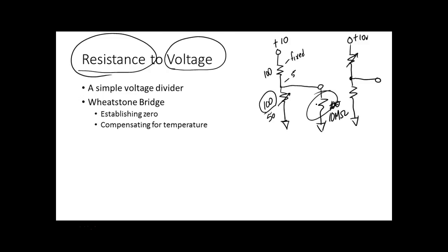But we've got a circuit, and we'll look at it if you take solid state, where we have to consider the resistance of the meter. So as long as I'm measuring 50 ohms or 1K or 10K, and I'm putting a 10K in parallel with 10 megohms, you calculate the resistance, it's going to be 9.999K, right? You understand? It's all practical purposes. But if I come over here and this is 10 megohms, and this right here is 10 megohms, then I've changed my circuit.